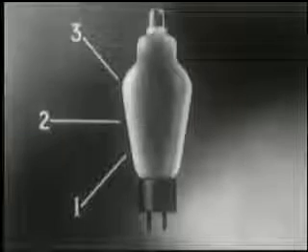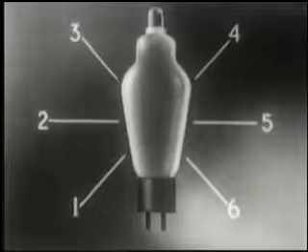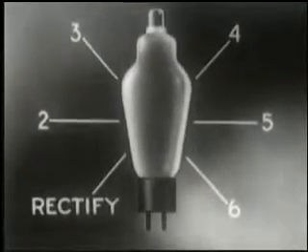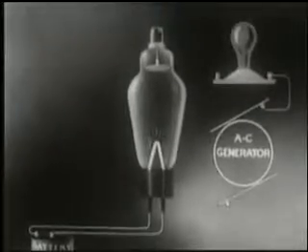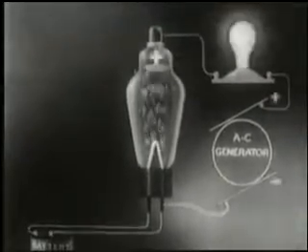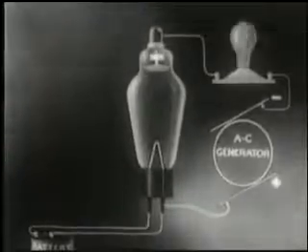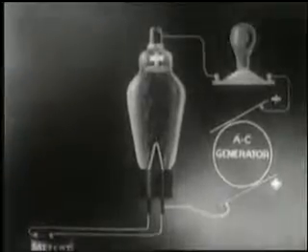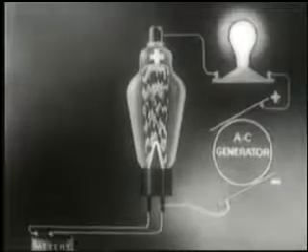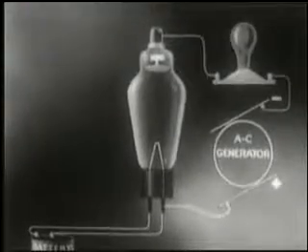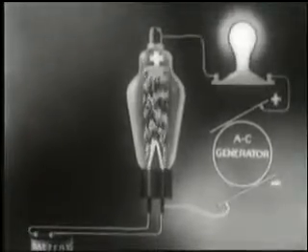Let's review 6 of the basic things that we can do with this new kind of switch. In the first place, we can rectify current with it, converting AC to DC. We can do this merely by connecting an electronic tube in series with an AC circuit. As you study this circuit diagram, note that only each positive half wave of AC voltage will now produce a current. When the anode is negative, the electrons are repelled and no current flows. In other words, because only the cathode...